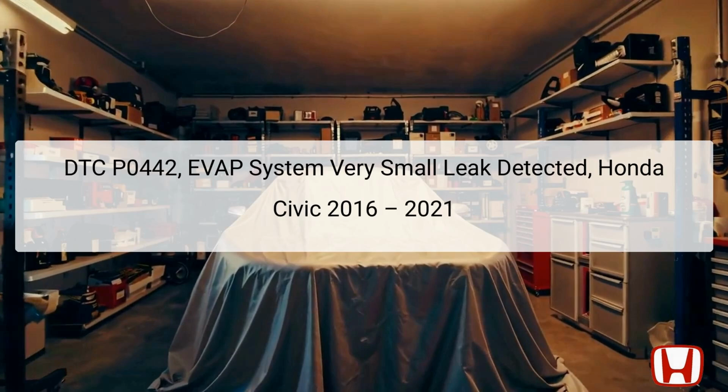The error code P0442 indicates that the vehicle's evaporative emission control system, EVAP, has detected a very small leak in the system. The EVAP system is crucial for preventing fuel vapors from escaping into the atmosphere, thus reducing harmful emissions. Components involved include the fuel tank, fuel vapor lines, and the EVAP canister, which is usually located in the rear of the vehicle adjacent to the fuel tank.